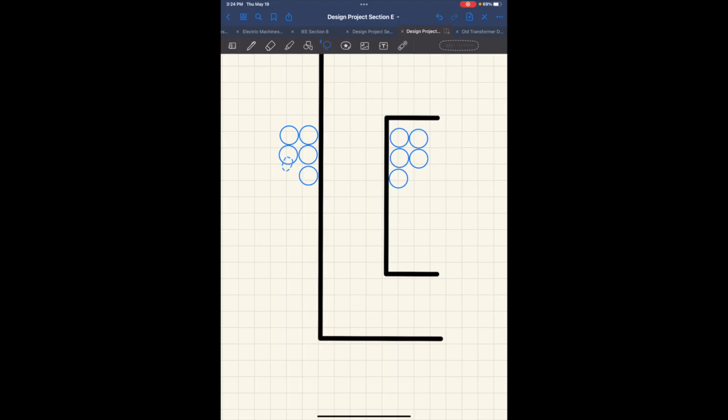So in other words, let me finish this. I wrap it once, and I wrap on top of it again. That basically gets me more turns without taking up too much vertical space. Because if I just do one layer, the vertical space I need is 57 inches. That's huge, right? So I can double the layer, and then that'll help me shorten the height that I need.